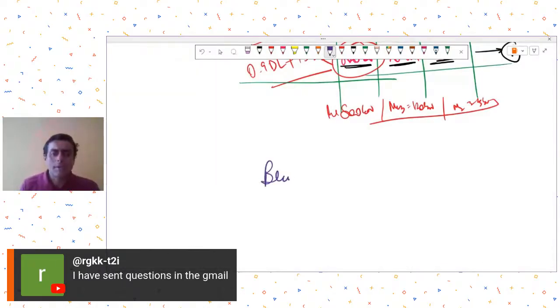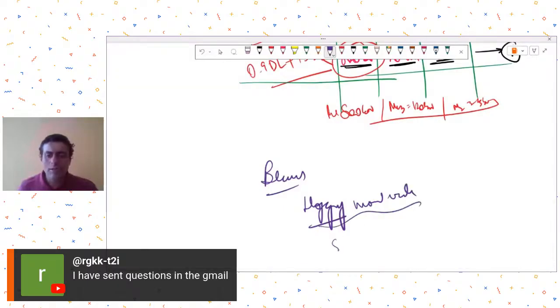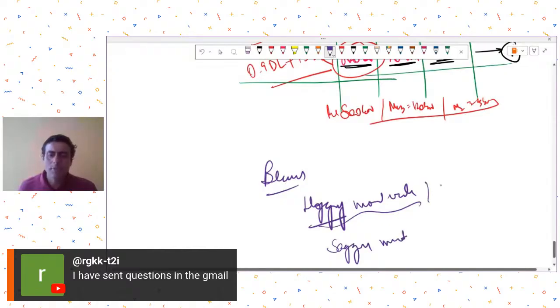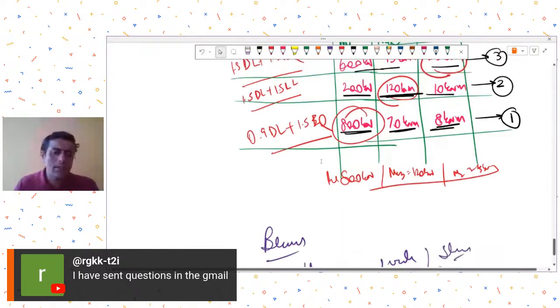Because as I told you, if you are getting some hogging moment and you take the enveloping hogging moment and just design for it, the hogging moment value will not affect the design for sagging moments, isn't it? Or the hogging moment value will not have any effect on the design for shears. So for beams, it does not matter as such whether you take enveloping values or not. But for members like columns, footings, where there is an interaction between different actions, taking enveloping values is incorrect.